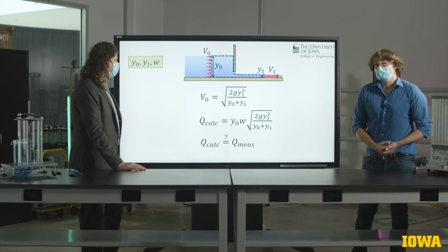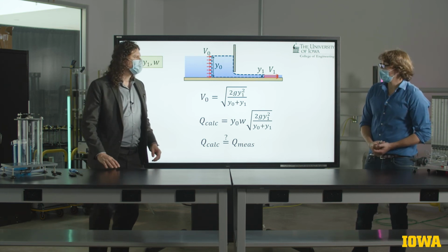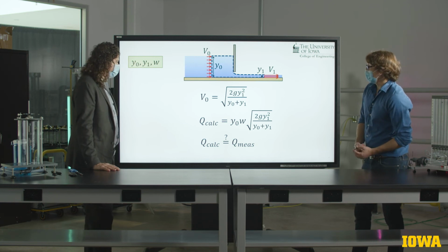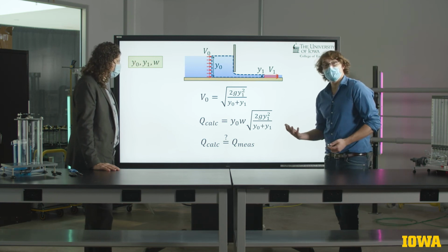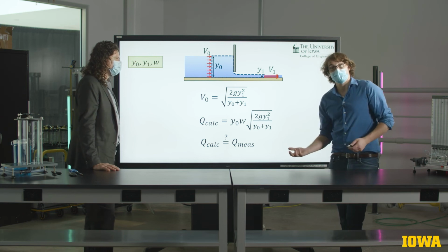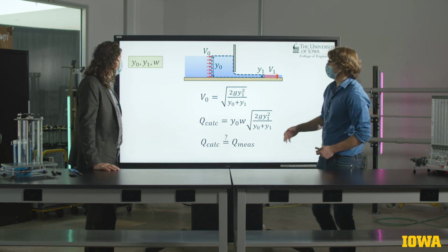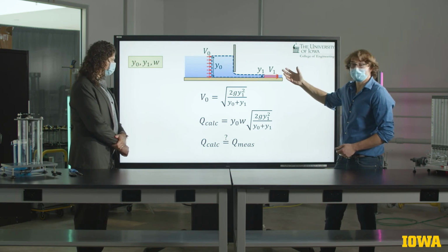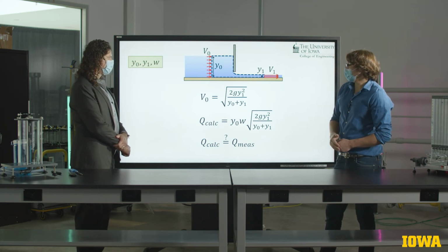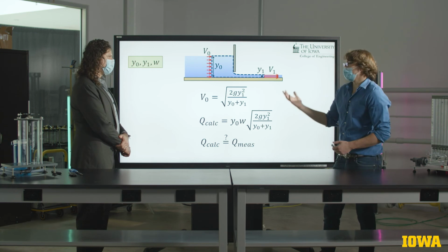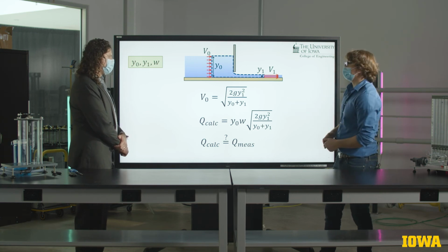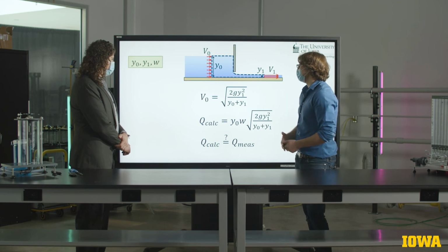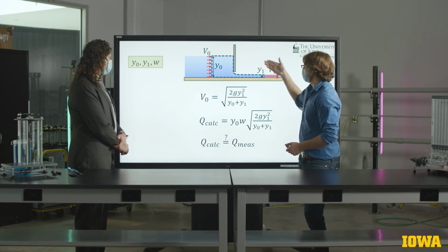The other thing we'd like to know is how correct our application of, say, conservation of energy really is. So you may recall we used an instrument called a mag-flow meter to measure the actual volumetric flow rate through our sluice gate electronically. Now, we'd like to compare this to the result that we get from our control volume analysis. So using our conservation of energy expression, which gives us V naught in terms of the difference in elevation